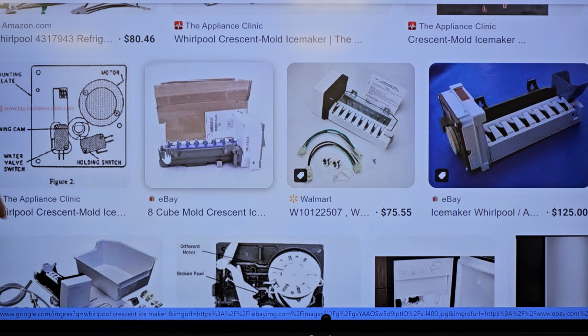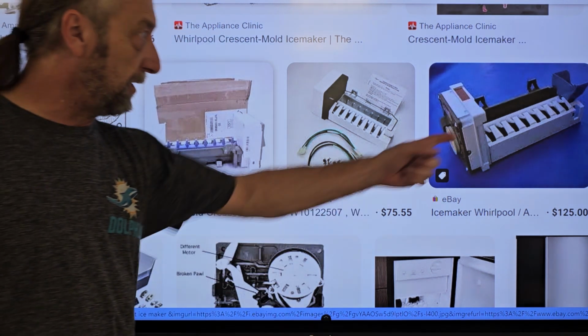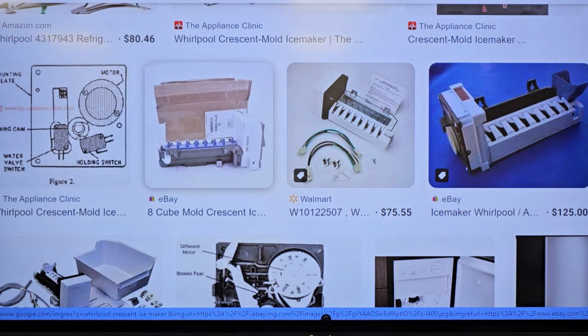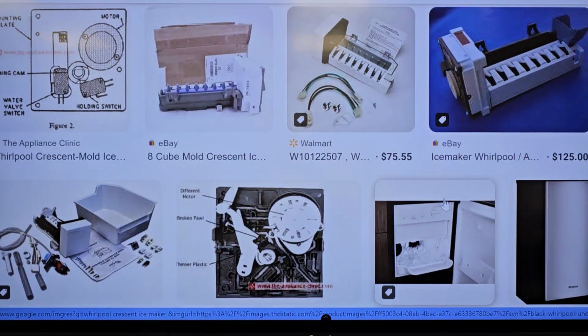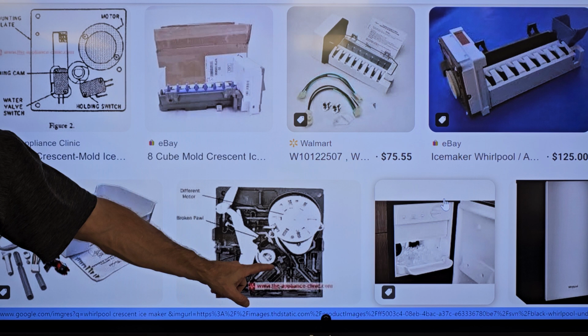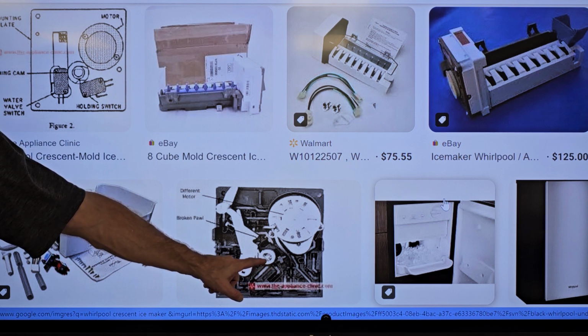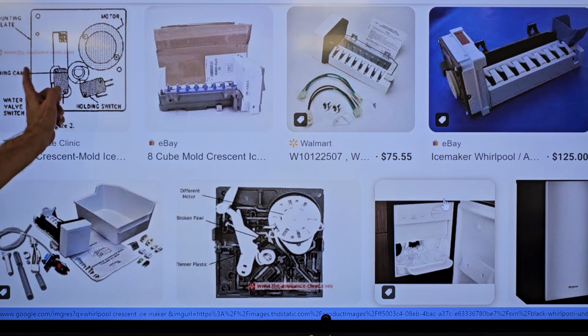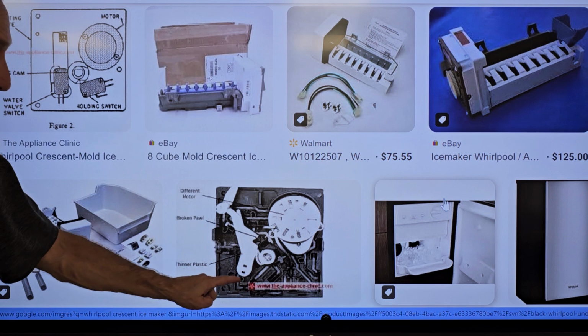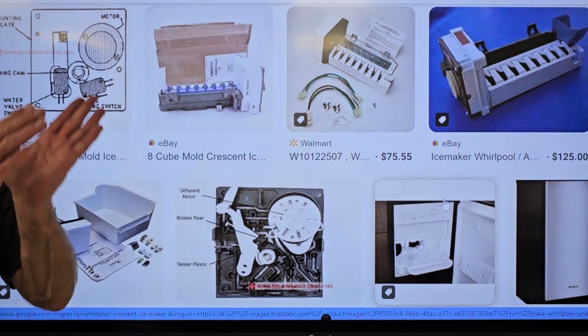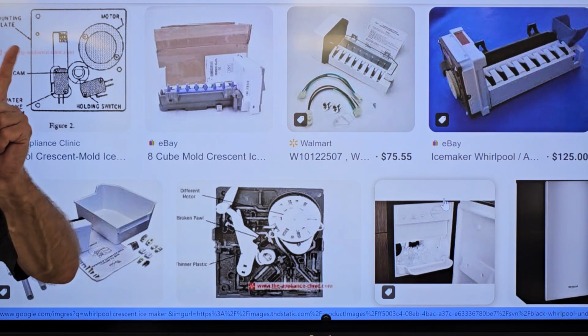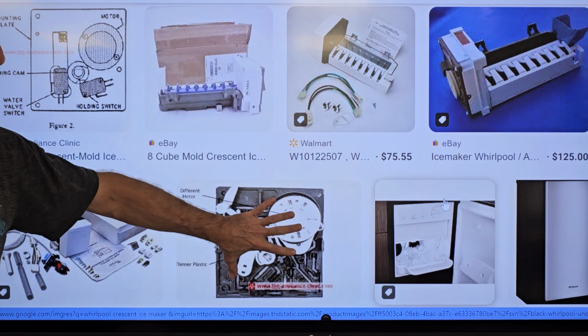And on the other side there you had a plastic gear, similar to the gear I showed you on that other ice maker. And they put three individual micro switches in there, one for water, one to control the cycle of the unit, and I forgot the other one. But then they went to this. This has no physical switches like this. It just has a motor. The switches are underneath this plastic. It's just two metal pieces that the plastic is opening and closing. And they called this a module.